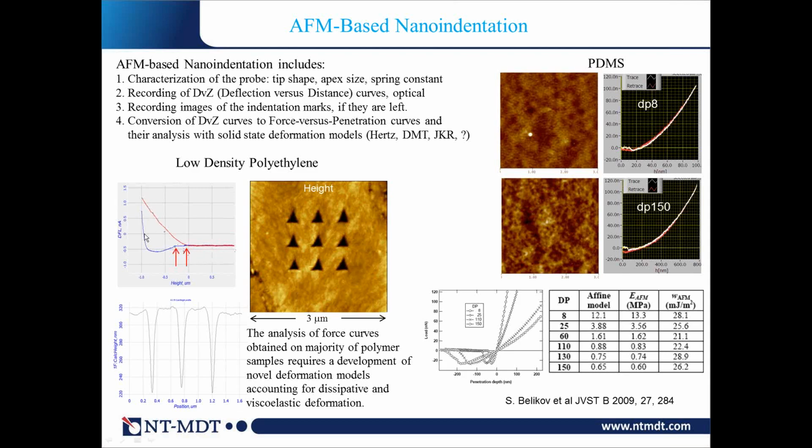However, what you see, this is after you've done the process. When you're doing the process, this is a force curve. You see the tip on the way back left here. And there are some distances here, probably around 200 nanometers. When we measure the left marks, they are only 100 nanometers. That means between the process we did and the image we get, the material recovered half of its deformation. That shows that this is not an elastic process. There are little components related